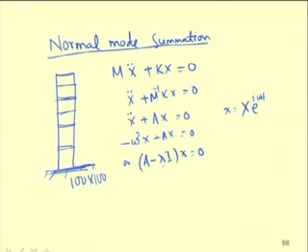Here lambda equals omega squared. By finding the eigenvalues of the system, one can find the natural frequencies of the system, which here are 100. But to find the response of the system, one may not require all these 100 modes. Only the first few modes may be useful for finding the response of the system.